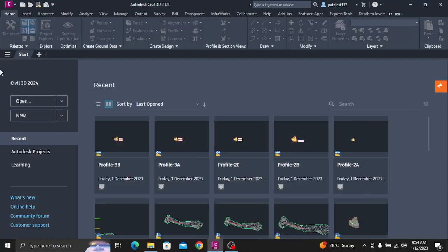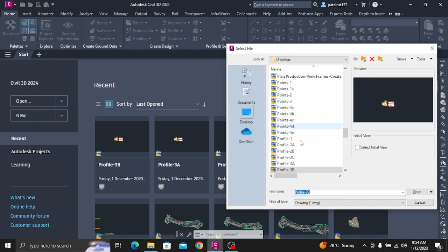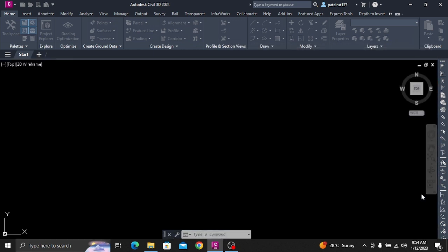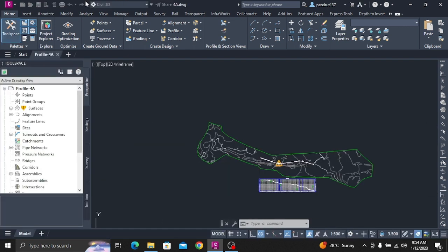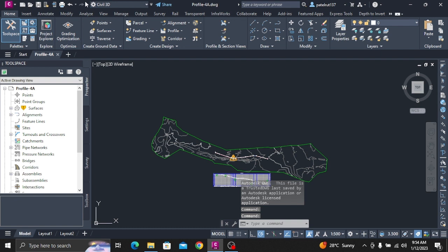In the left viewport, select the 3D polyline in parcel 101. On the command line, enter list. In the AutoCAD text window, notice that the elevation values for the polyline vertices are approximately 38. Press enter. Close the AutoCAD text window.